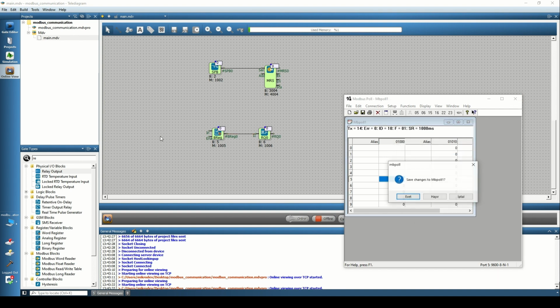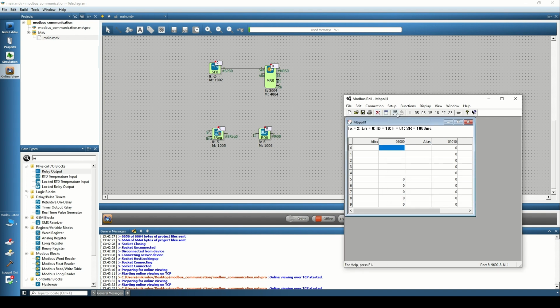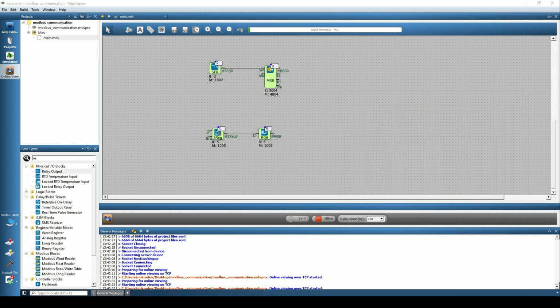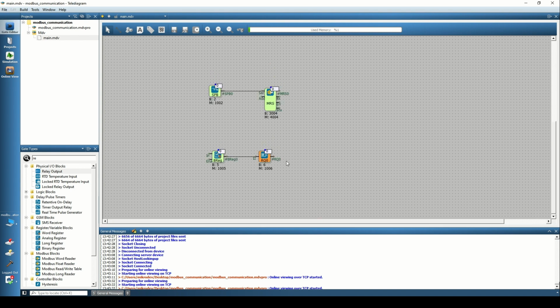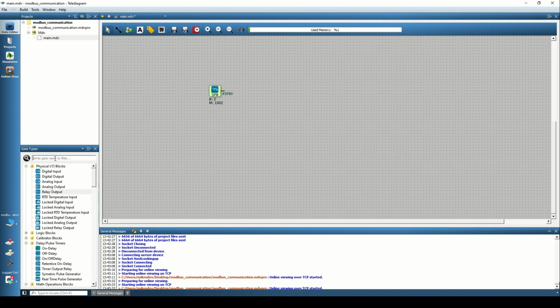When we set on, it became 1 on the device, and we saw that it triggered the relay control. When we set off, we saw that the relay returned to position 0 again. So, we performed control via RS-485. This could have been an HMI screen for read-write operations. When the HMI is the master, we saw how the PLC is used as a slave.